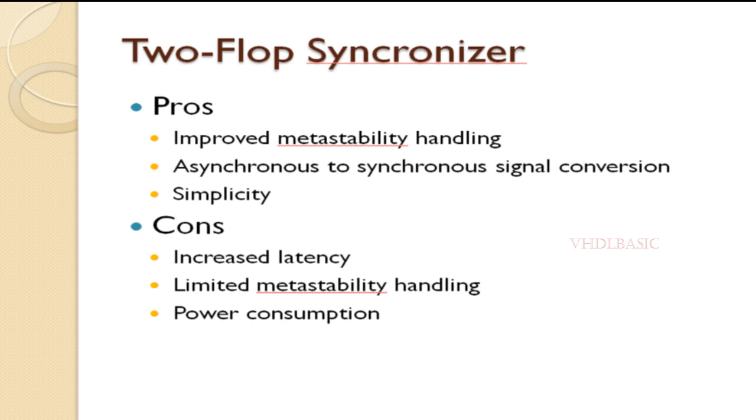Asynchronous to synchronous signal conversion. The synchronizer allows you to safely transfer an asynchronous signal to a synchronous domain without violating the setup and hold time requirement of the receiving flip-flop. It helps ensure proper synchronization and avoids data corruption. Simplicity. The two flip-flop synchronizer is relatively simple to implement and understand. It requires only two flip-flops and a few combinational logic gates, making it easy to integrate into a larger design.